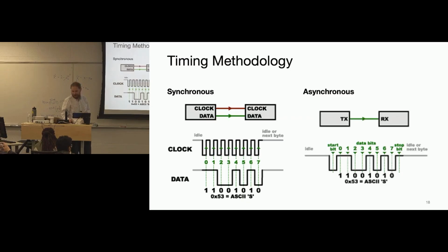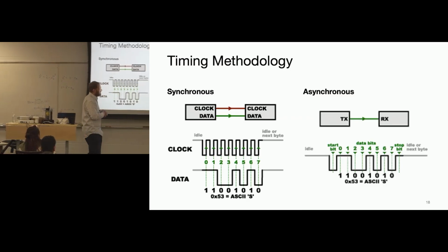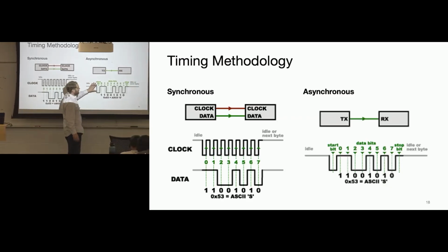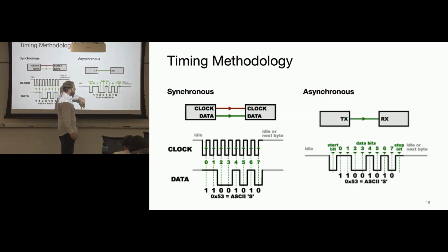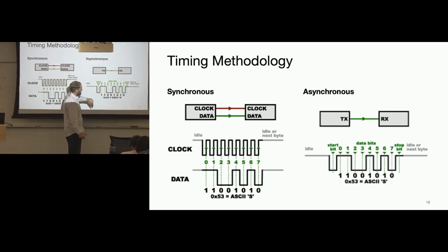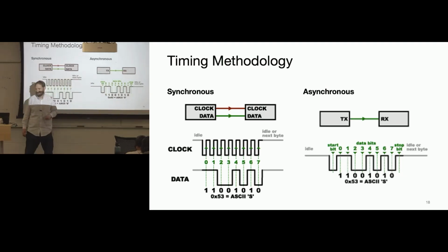Is it like all software that controls the clock? Like how do you know? Usually it's a hardware peripheral. We don't want to put programmers in charge of making sure time-critical things are happening. We'll talk about some of those methods when you get to some of the later bus protocols, but there's usually hardware methods to help you figure that out.